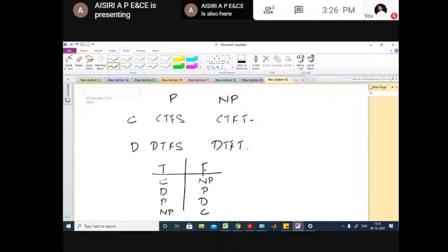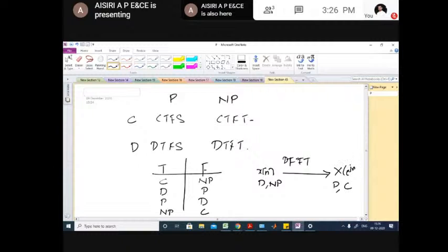So for example, say I have the discrete time Fourier transform being applied on x of n. Usually this is applicable for discrete and non-periodic signals. When I apply the DTFT, discrete becomes periodic, non-periodic becomes continuous, which is nothing but x of e power j omega or x of omega. So this will be continuous and periodic. Okay. So the problem is that this is continuous and periodic, so we cannot have infinite values to store the frequency domain representation of x of n. So we sample the DTFT to get the DFT.